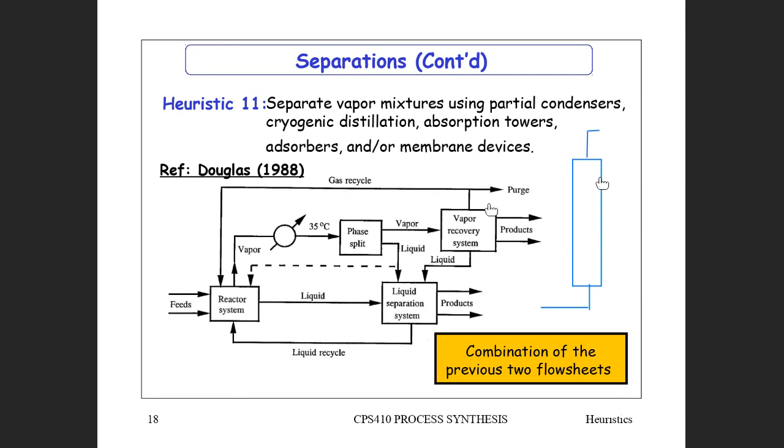Assuming the need to distill and require the addition of something else, how would we separate the added mass agent from the other component? If it's even necessary. It is necessary. If you're going to add what we call a mass separating agent that helps the separation occur, you've got to recover it. But you can use distillation. You can use normal separation techniques to recover that. You're going to choose it so that it is easy to recover.